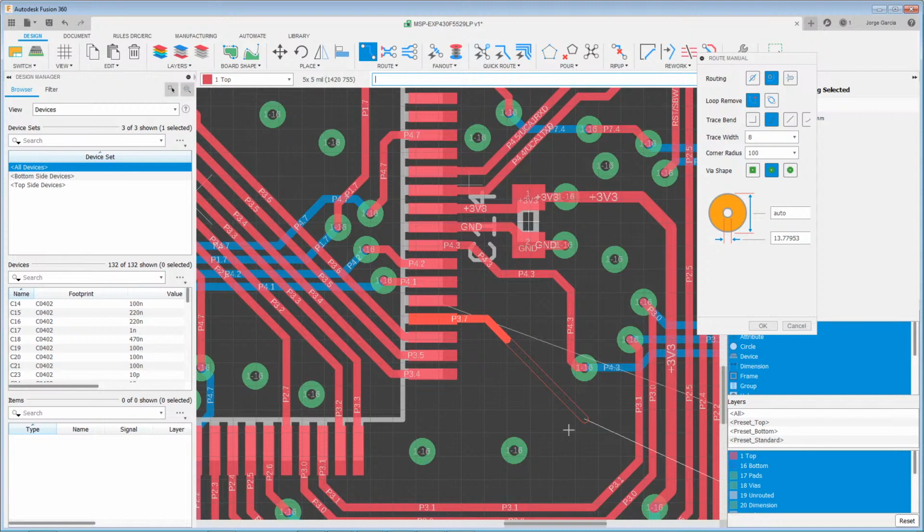Okay, if you're familiar with AutoCAD and many of the other Autodesk products, there's a mode called Ortho which makes it easy to make a straight line. So if you needed to make a long straight trace, you just hold down control and it'll maintain its angle. Makes it very easy. Okay, and it'll snap in 45-degree increments. So once I'm closer to there, you see what it does?